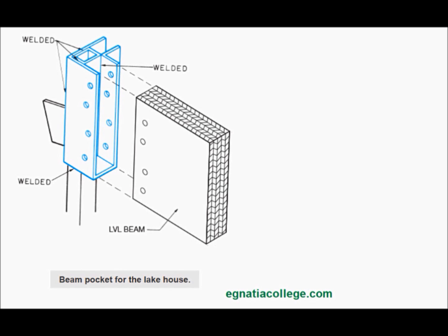However, this is not purely post and beam construction. The posts are 3.5 square steel tubing, and the beams are LVL beams. These are properly called beams because they carry a load without continuous support from below. These beams are supported only in the beam pockets on the steel posts. In this house, the post and beam construction does not include exterior walls.